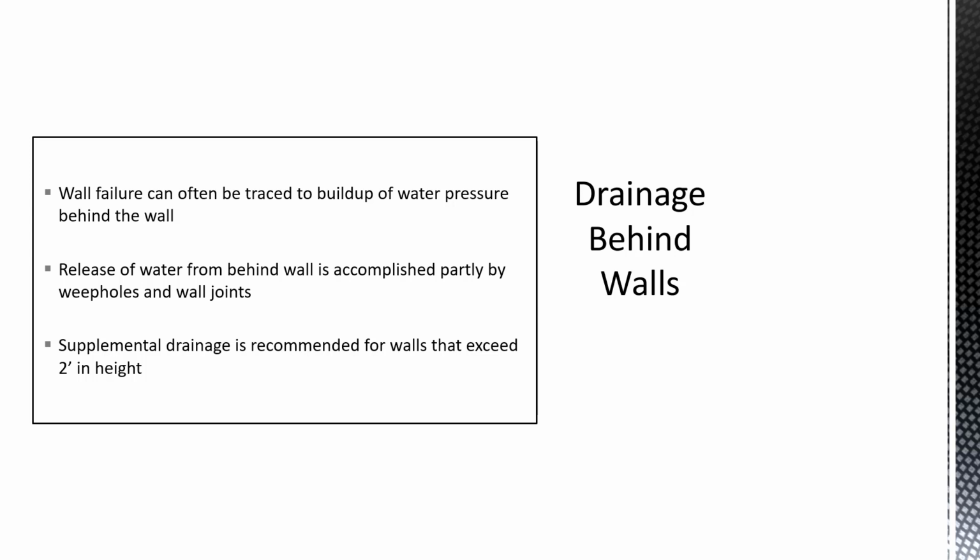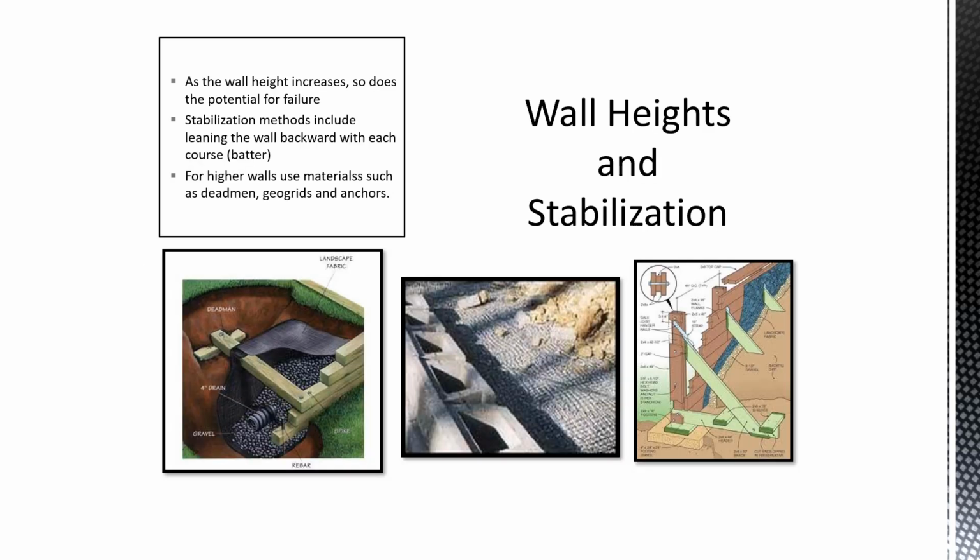You got to have that pipe behind it, with either corrugated. Usually it's a corrugated that has the slits in it or actually has the perforations or the holes. So you got the perforated pipe with the holes that you're going to put gravel on top of. And then you may have the slit corrugated pipe that's either going to be covered in some type of netting or almost like a pantyhose material to keep debris from getting down into the pipe.